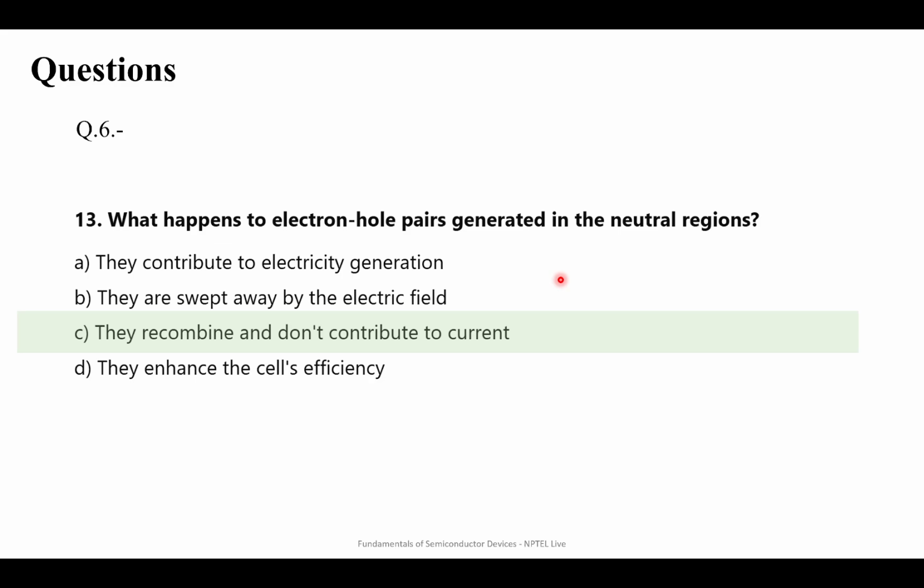And so now the p-type region has an extra electron. That extra electron can't be absorbed because there's no available hole for it to recombine with. So it will just go to the edge of the p-type region and go out. Similarly, the hole will go out on the other end. That is how we can collect electron and hole, and that's how we will get an electric current.